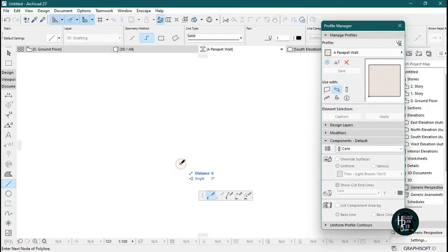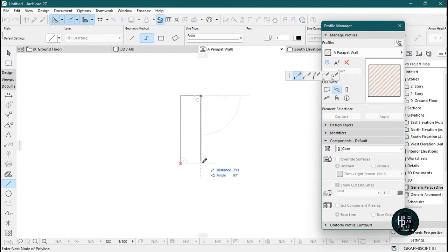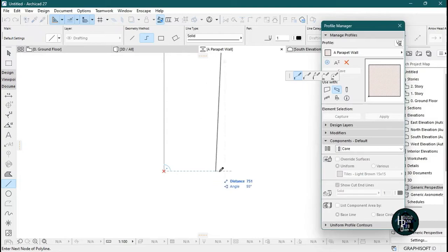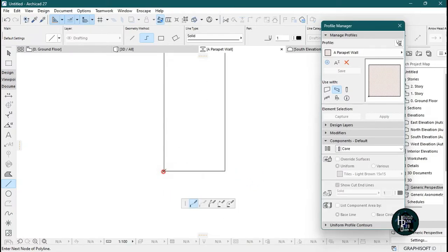I want you to click on the X, drag it up, and let's give it a distance of 750. Click enter, take it back like this. Okay, or rather take it forward and let's give it a distance of 225. Click enter, drag it down, and make sure that you are seeing that dotted line being formed, so you can have the exact level of this point. So just click this point and let's double click this side here.